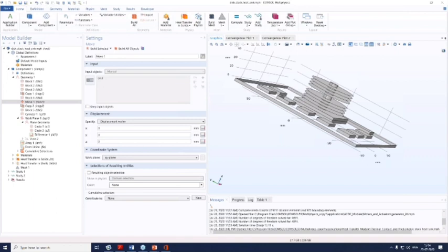Even though it is just a cube over here, you might be having some complex geometries. So always ensure that the absolute tolerance will be calculated based upon the maximum coordinate of your geometry times the relative repair tolerance, if you're mentioning the tolerance in terms of relative repair tolerance.